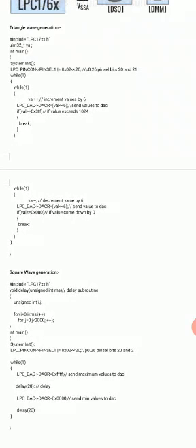Earlier, when we were using other registers like FIODIR and FIOPIN, we used LPC_GPIO. Here it is LPC_PINCON. PINCON stands for pin configuration, since we have to set the functions for the pins. That's why we use LPC_PINCON, not LPC_GPIO. So remember, LPC_PINCON->PINSEL1 is ORed with the value, because some of the other pins apart from P0.26 are connected to some of the other modules. You have seen in the LPC 1768 board,